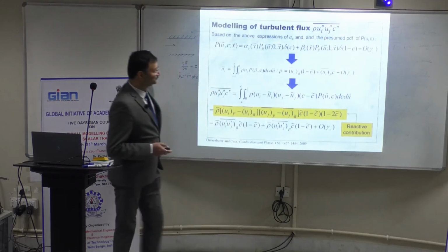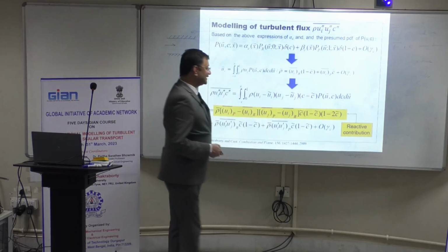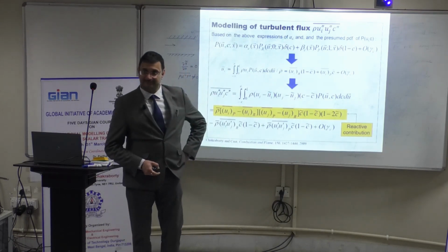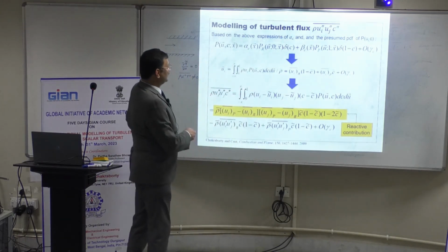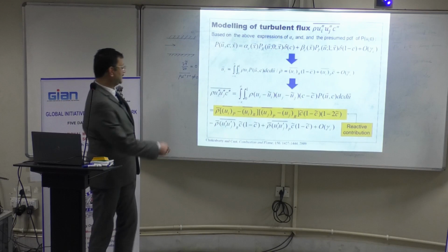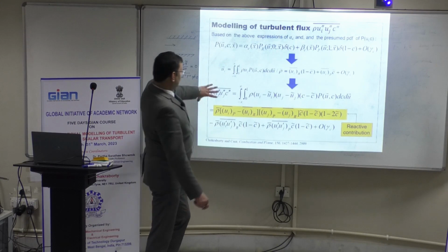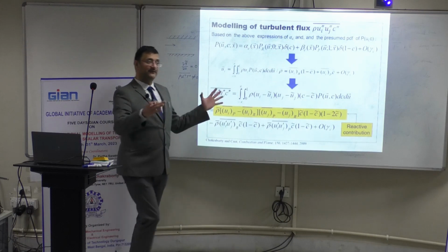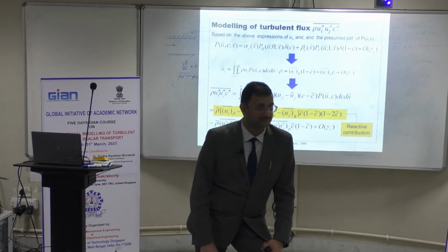Modeling of this, if you follow the same procedure as I talked about, Ui double prime is Ui minus Ui tilde by definition. Uj double prime is Uj minus Uj tilde. And then if you actually do the algebra, you have it like this, plus essentially this contribution. Whatever you are seeing is essentially a function of this quantity, slip velocity. If you don't have any heat release, the slip velocity is going to be 0, right?